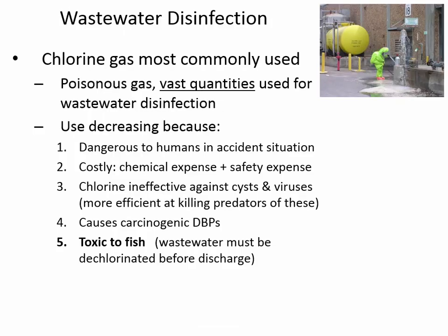Let's talk about disinfection. There are some similarities between wastewater disinfection and drinking water disinfection. We can use either chemical methods or physical methods to do that. And by far the most common disinfection method that's used these days is chlorine. And it's just mainly because that was the first disinfectant, and there's the inertia of once you've got something, you tend to stick with it when you've made the investment to purchase all of the equipment.